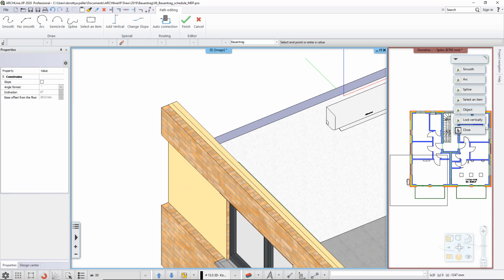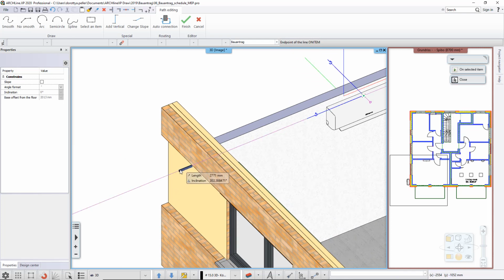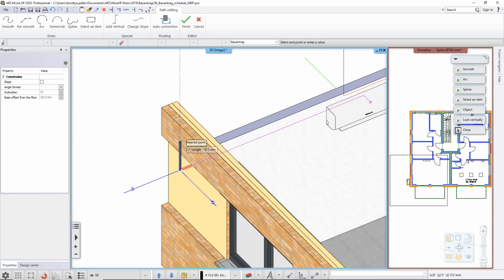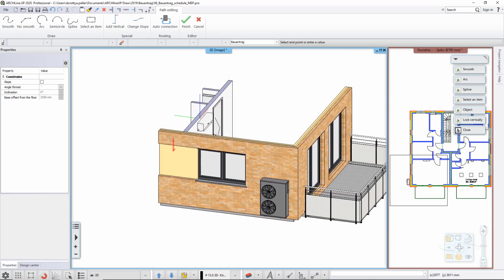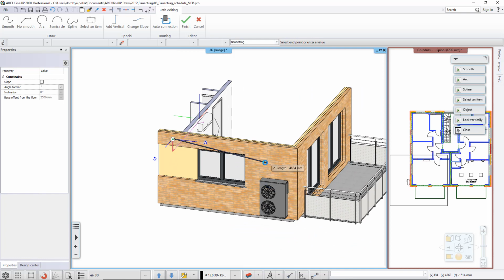The internal walls would have the pipes in them, but outside they are just going to be visible. So we are going to start creating the route up until this point, where the software is going to give the bends and the edges, the elbows automatically. But I don't want to do all this job manually. I want to connect the 2 points. How do I do that in a very easy and accurate way?